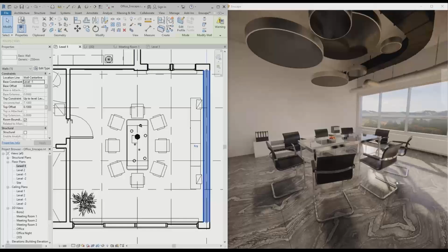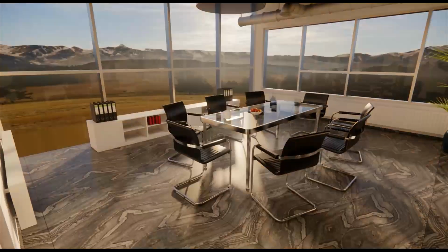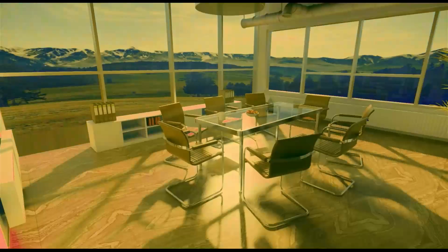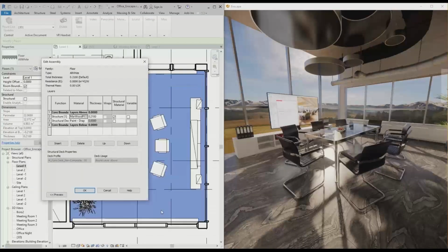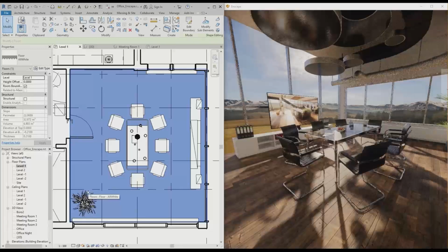So we're really doing exactly what we talked about in that example right here. So we've got Revit open, and we've just changed the solid wall to a transparent curtain wall, and all of a sudden we can see how the lighting level is changing in the space. We can see what impact that has. It's obviously a lot more light, and so therefore now we're going to respond to that change with changing the material of our floor. And we've gone from this tile to this wood now, and we can see that the light is interacting with it in a completely different way. And now we can even change the time of day, right?